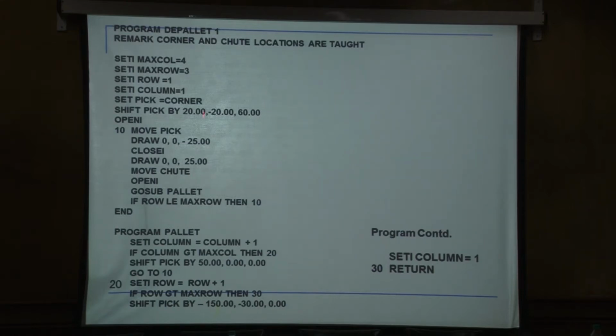Okay, so this is an example of a robot, a 6-axis robot, where we have to do the experiment also. So we'll be using simple commands like open, move, close, open, approach, depart, and then you can write the program. So this we'll do an experiment, and then you have to write the program by yourself. So you can make it do different things. For example, you can make it draw a circle, you can make it draw a rectangle, do all kinds of motions. Okay. So simply by using this set of commands.